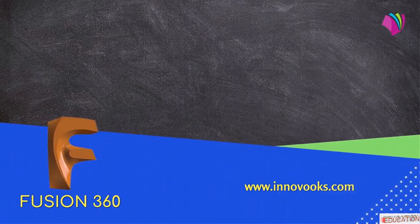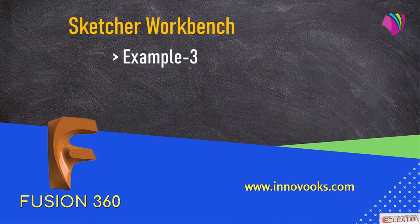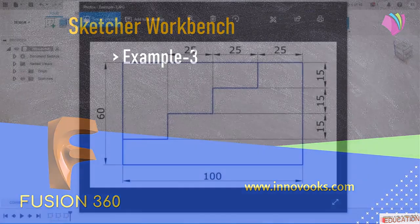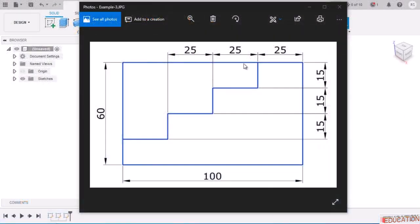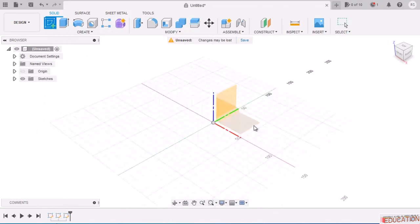In this lecture we are going to generate a completely constrained geometry of example 3, which is this. This is the drawing that we are going to make now. So let us start. As usual, we will select a plane by clicking on this create sketch, and we will select this XY plane.